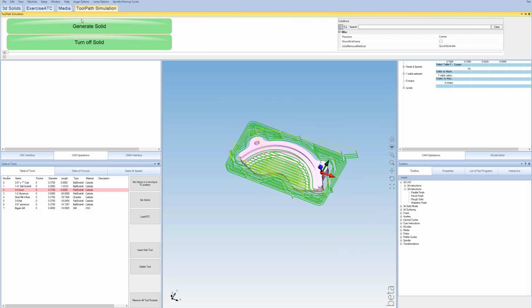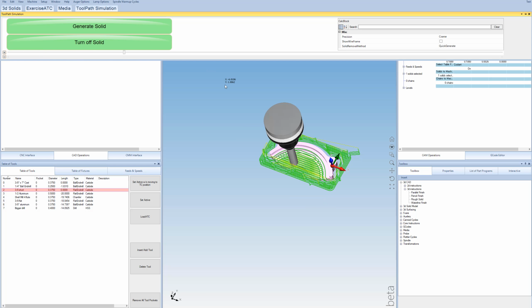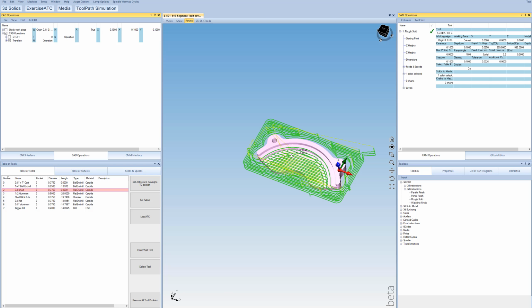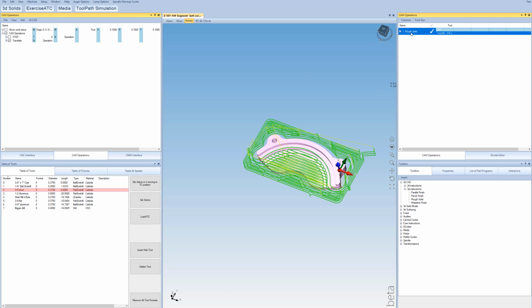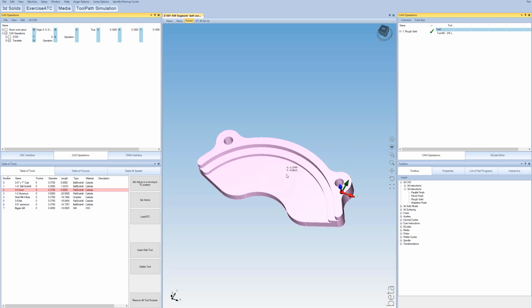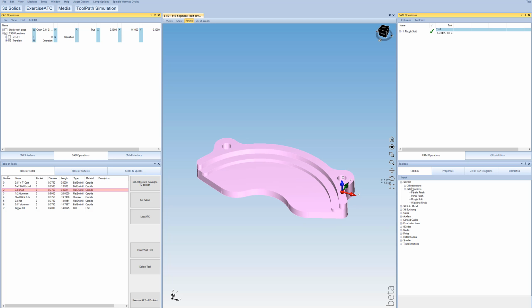Before we move on, we can also do a toolpath simulation, just to make sure it's something like what we're looking for and it looks good. It's just going to go all the way around the perimeter and cut the whole thing out. Okay, so then after that, we want to save that because that's going to be part of our ongoing program. We're going to save this file at some point, and this is going to be our master program. Okay, so once we do that, we've basically milled everything down, and we can start doing some finished work.